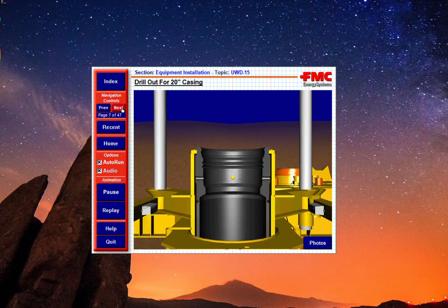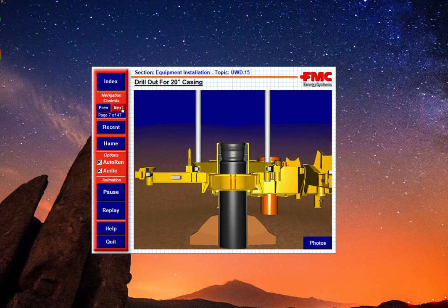The hole for the intermediate casing is drilled through the 30-inch conductor pipe to a pre-established depth. The cuttings transport system is utilized in this operation. The 18 3/4-inch subsea wellhead assembly is connected to the last joint of casing. An 18 3/4-inch cam actuated running tool is installed in the wellhead. The casing is lowered and landed in the 30-inch wellhead assembly.